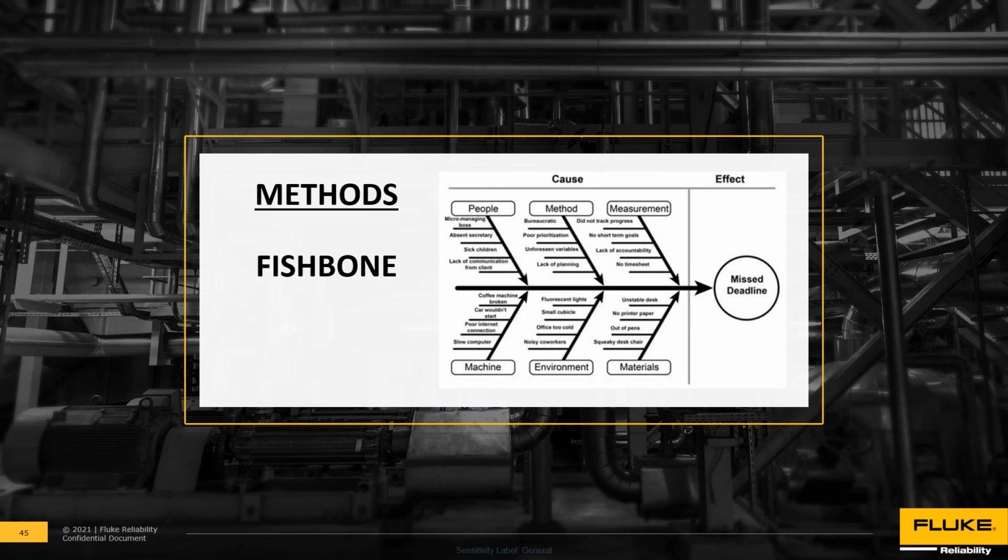And I brought in the manufacturer. The guy came in and he actually admitted to me, he says, well, when we were designing this machine, the stacking part of it was kind of the last section of it, and we just didn't really spend as much money on it as we should have. So it wasn't really the greatest design to begin with, and I ended up getting a scissors lift, getting rid of the whole chains and just using that for the discharge. So you can run into things like that.